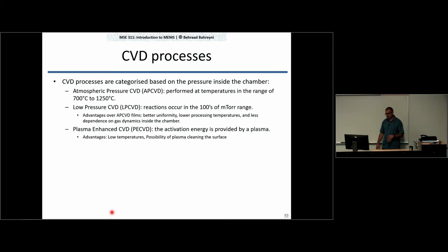So this is called plasma enhanced CVD, happens at 200 degrees Celsius or maybe even less, and it gives you a lot of control. Like other plasma systems, you can play with the pressure, you can play with the gas concentration, you can play with the gas ratios, and also temperature too, right? It gives you a lot of buttons to press to tune different parameters.